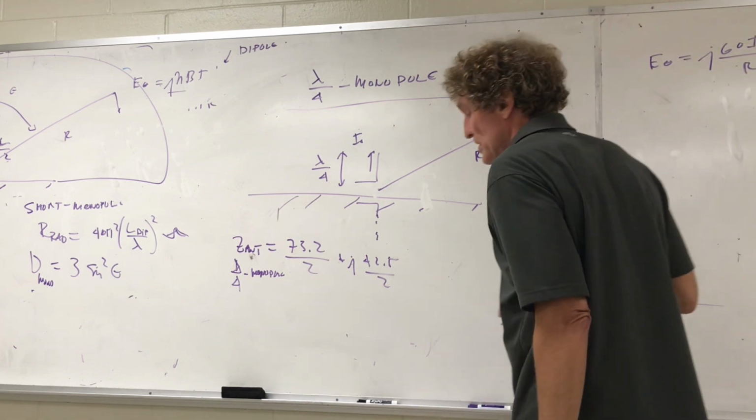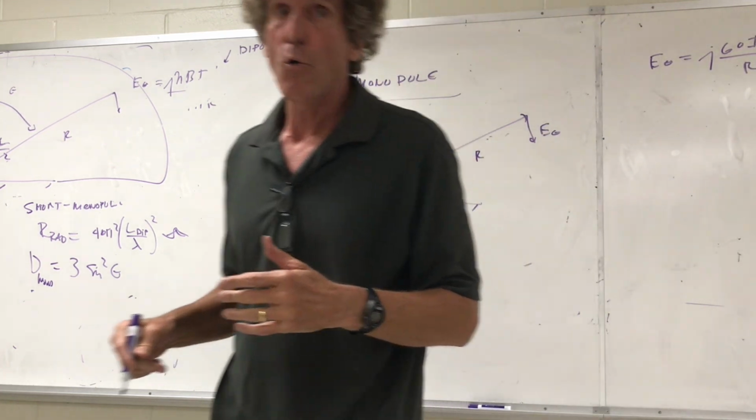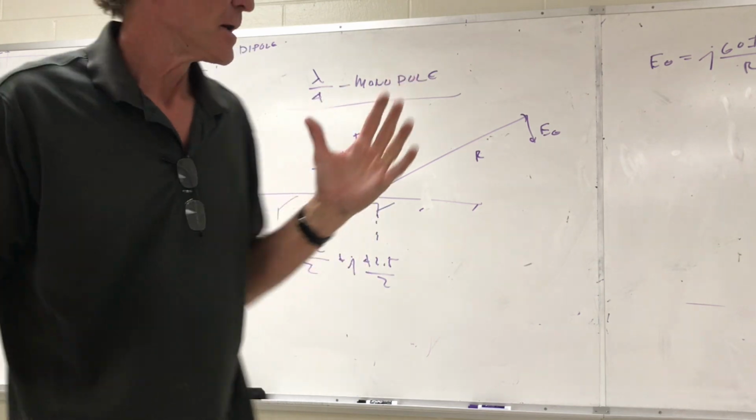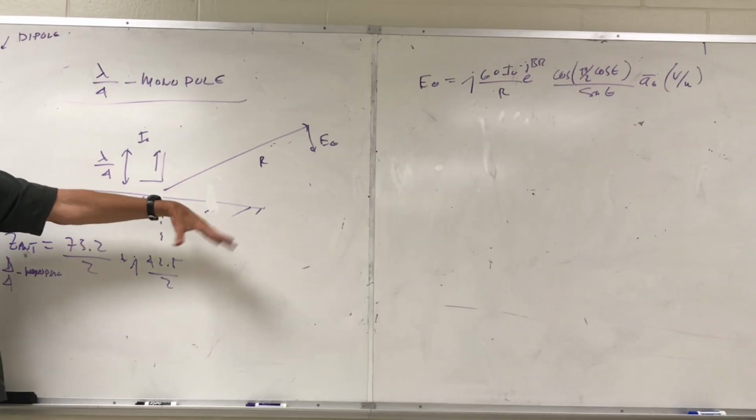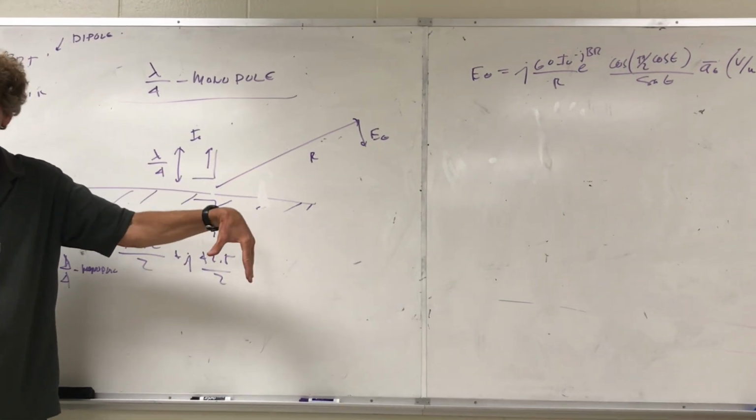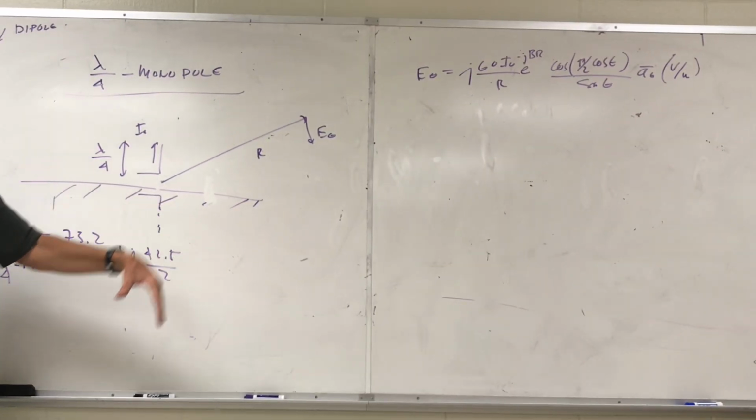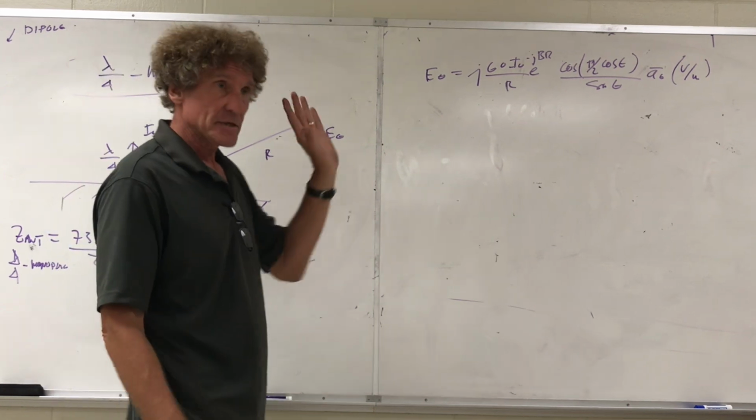You're going to get the same power density, only in the upper hemisphere. Remember, it can't radiate below the ground plane. Nothing radiates below that, it's a perfect conducting plane. The power density out there will be the same.